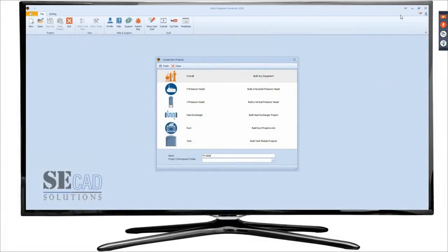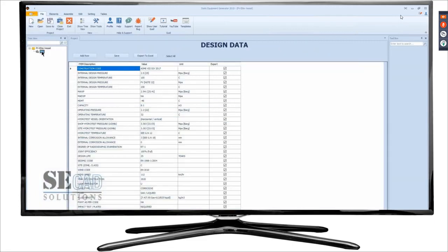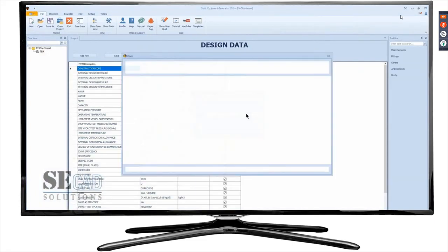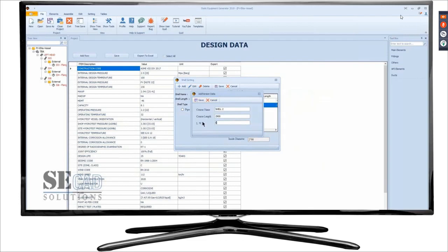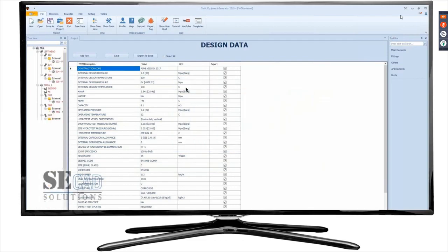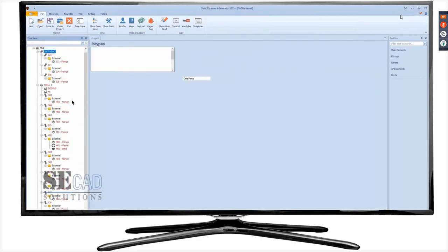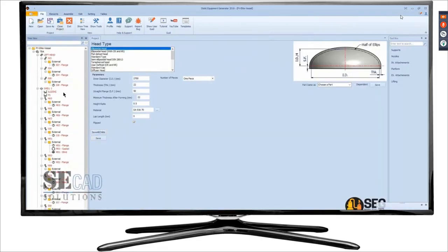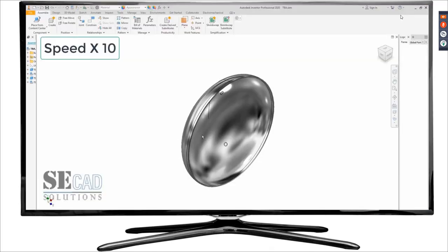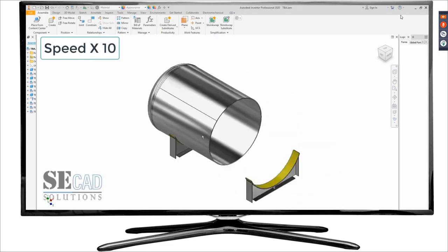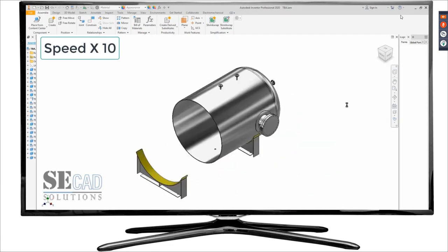Here in this video, we use this integration tool to create a pressure vessel created by BDL, and here we will import the exported database file from BDL and modify some data during importing, like longitudinal welding line orientations of the shell courses. After that, you can see that all the tree is built automatically according to the imported data from the Access database file. Now we will save the data of the equipment. After that, we will proceed to create the 3D model of the equipment. Like that, you can see that all items will be created automatically and assembled automatically for the equipment.